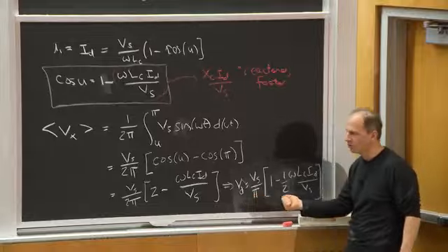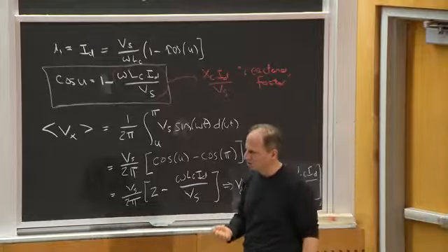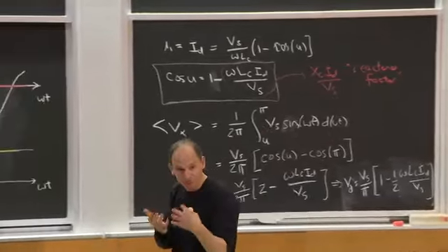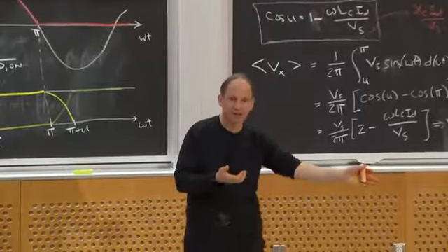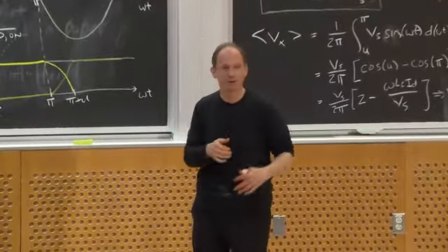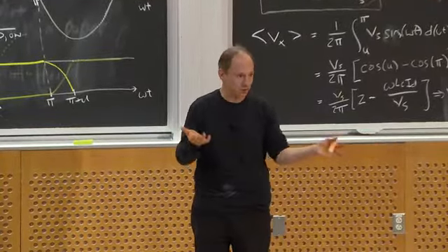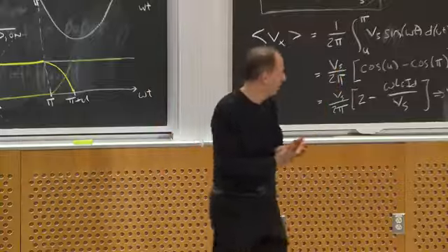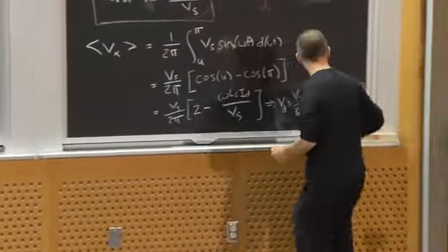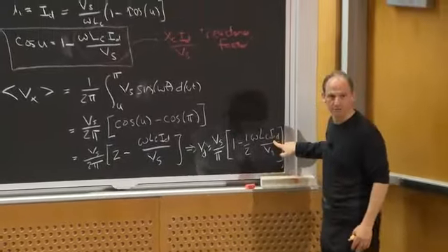So suppose I generate this high frequency voltage, and then I rectify it expecting to get, in this rectifier, Vs over pi as my output voltage. And suddenly I do that, and what happens? Well, I get this droop that's load dependent, right?